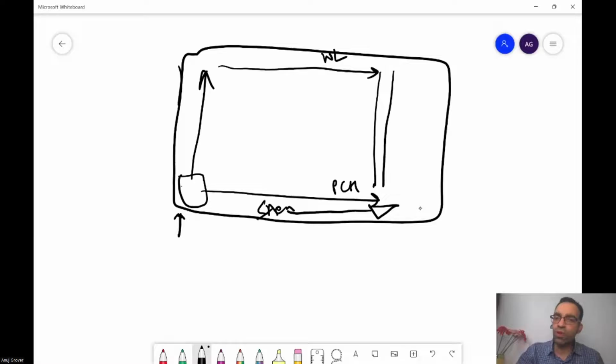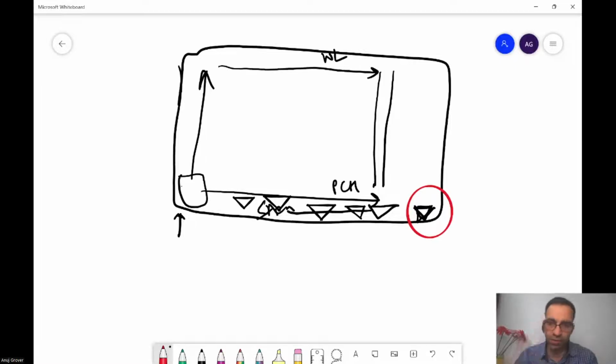Yes, sir. What is the worst case at which offset will be created for any sense amplifier? Which sense amplifier will probably have the worst case offset? There are sense amplifiers all over the memory, right? Which is far from the decoders or something. So you are saying that this particular sense amplifier will have the worst case offset. The farthest one. Yes, maybe.